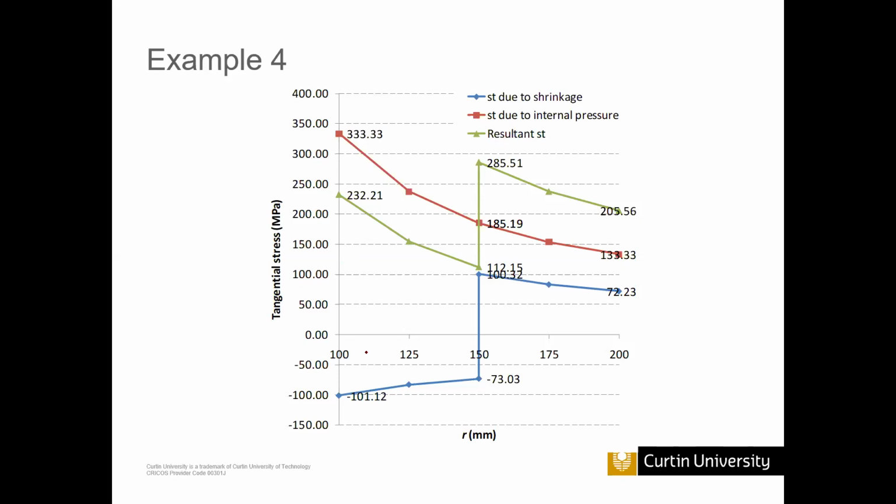And due to contact, the shrink fit, due to shrinkage, you can see at the inner surface, because of the outer cylinder, the inner cylinder tries to compress. So that is why there are minus values.